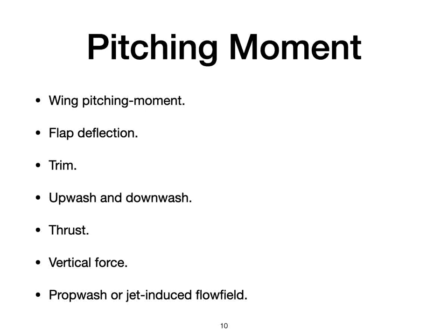The engine produces three contributions to pitching moment. First, the thrust times its vertical distance from the center of gravity. Second, the vertical force Fp produced at the propeller disc or inlet face due to the turning of the free stream airflow. Third, the prop wash or jet induced flow field will influence the effective angle of attack of the tail and possibly the wing.